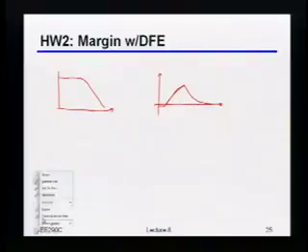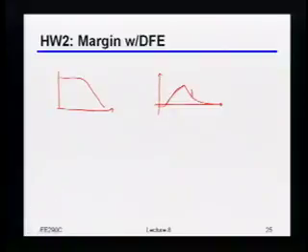Most everyone figured out that one thing that's interesting about this type of channel is that there's a very well-defined relationship between each and every value of the residual ISI. All it took to cancel all of the later taps was to arrange, at just one point, either a DFE or, in this case, the FIR, to put in exactly enough energy to cancel that one thing. Then all of the following taps would also be canceled because they were all just scaled copies of that same value. Right, so this worked particularly nicely on the transmitter.